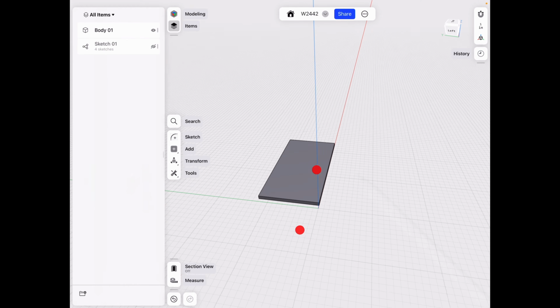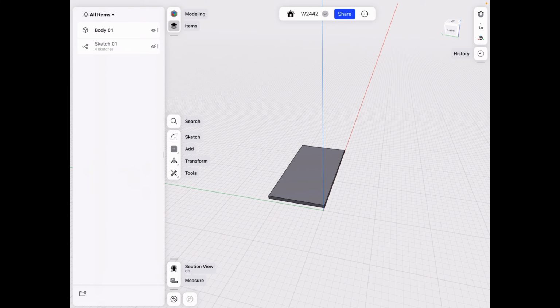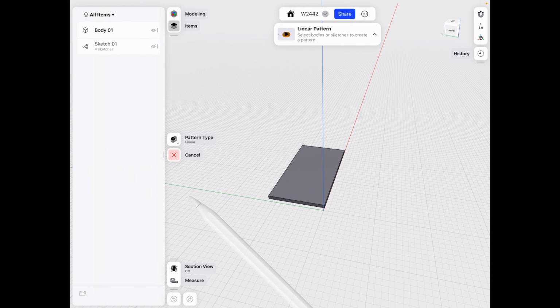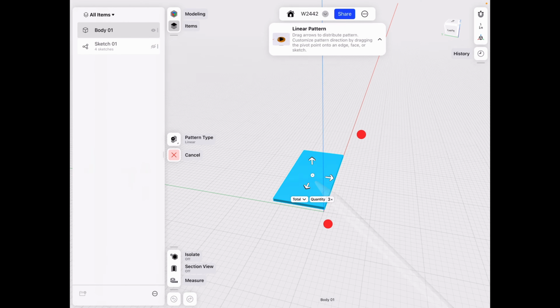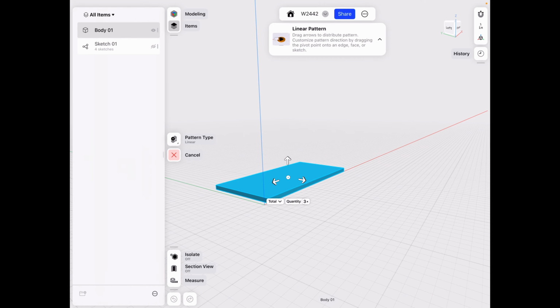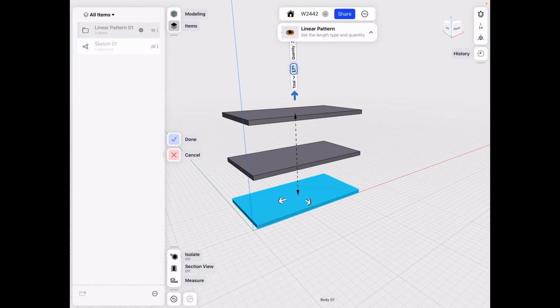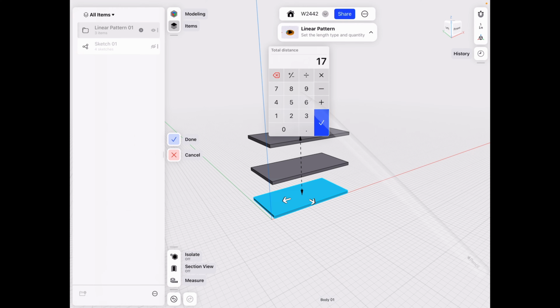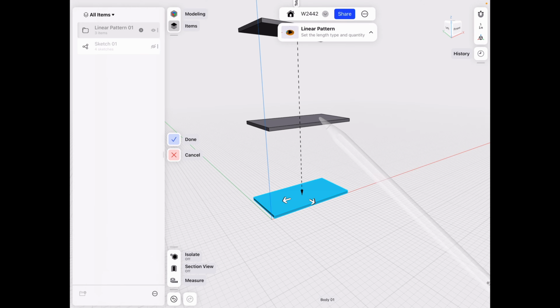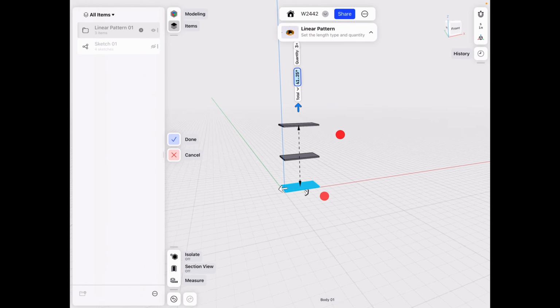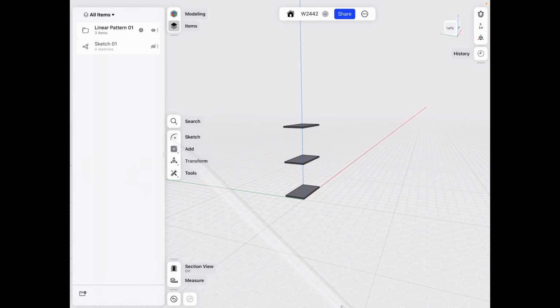And once we have this point, we now go to transform pattern. Okay, so double click your little slab there, or shelf, and then we need to go up to a total distance of 42 minus 3/4, that's 41.25, and we're fine at 3 for now, so we'll settle with that.